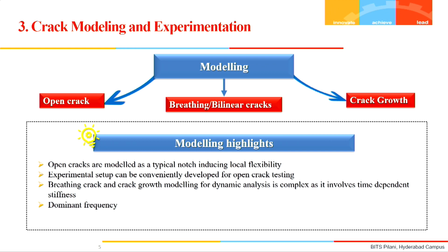Breathing crack and crack growth modeling for dynamic analysis is complex as it involves time-dependent stiffness. As I told, whenever we talk about the dynamic modeling of breathing cracks, it involves time-dependent stiffness, because as the crack opens up and closes, the stiffness becomes a time-dependent parameter, because the flexibility being induced depends on time, on the cycle of the vibration.